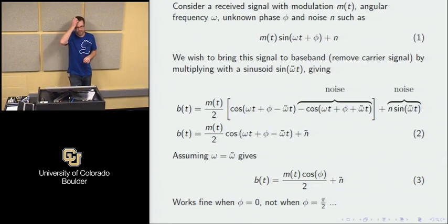Well, it's a couple of different things. It's maybe a little bit outside this class, but basically, super heterodyne is what is called when you mix it to another IF. So we have the 16 megahertz one, we mix it down to 4 megahertz, and then we do the rest in digital signal processing, right? We could do the same thing as what's happening on the next slide here, where we have two sinusoids that we mix it down with, an in-phase quadrature, sinus and cosine, and bring it directly down to 0. That works.